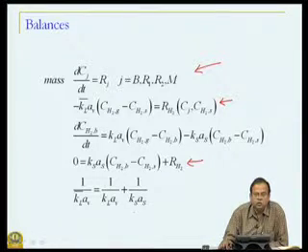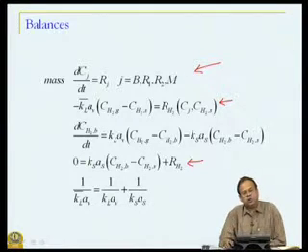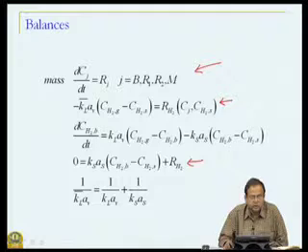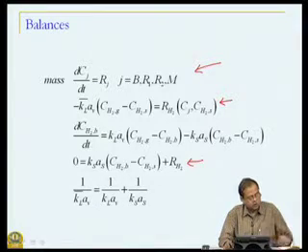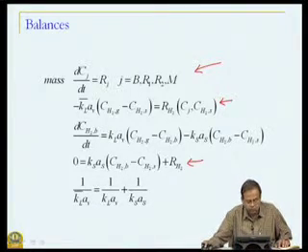So, I can now simulate my reactor if I know the initial concentrations of B, R1, R2, M or saturate S and the hydrogen concentration in the gas phase, because we just now saw that hydrogen concentration in the gas phase is in turn related to the concentration in the liquid.